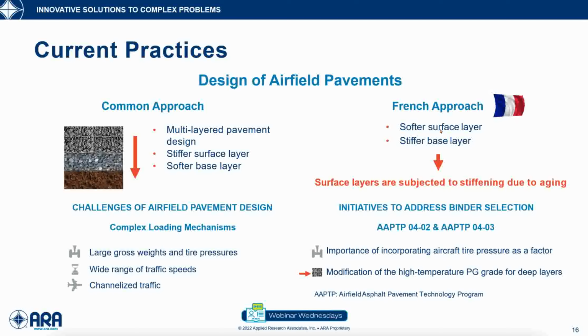Now, there are challenges and complex loading mechanisms in airfield pavement design, some of which are the large gross weights and tire pressures, the wide range of traffic speeds on a runway or a taxiway, and the channelized traffic of the airplanes. They all pretty much land at the same spot, particularly with the adoption of the ILS, the Instrument Landing Systems.